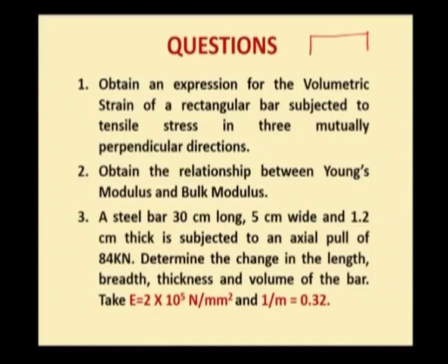Once again it is a rectangular bar. Length is given, breadth is given. Length is 30 centimeter, breadth is 5 centimeter, and the thickness is small t. It is subjected to a pull of 84 kilonewton, an axial pull.